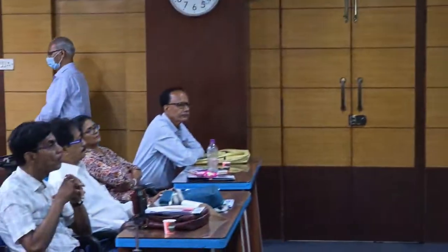That means you get an idea from the design point of view. If you want it to be within a certain designed limit, then you get an idea about how many times to run the mechanical sweeping machine, and at what intervals. So instead of just running it once a day or once in two days, you do it according to the amount of silt on the particular road type. So you can choose a different frequency of interval according to the amount of silt load on the different types of road.